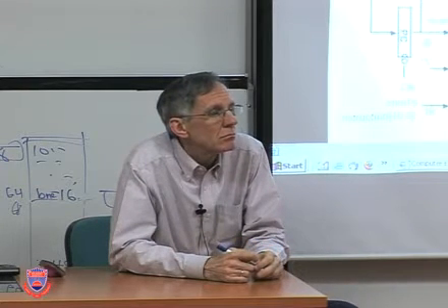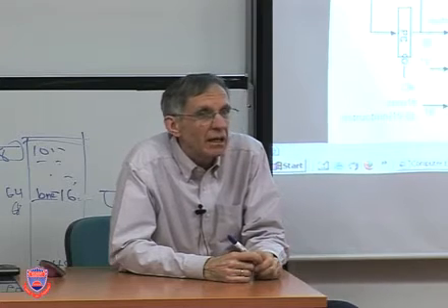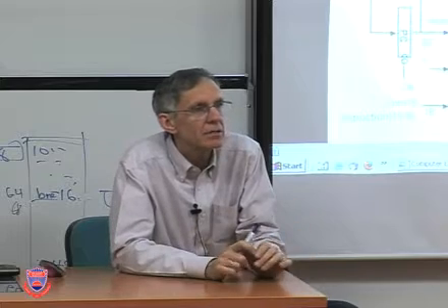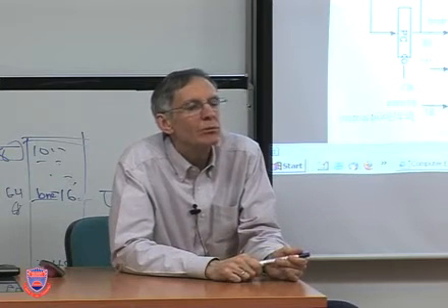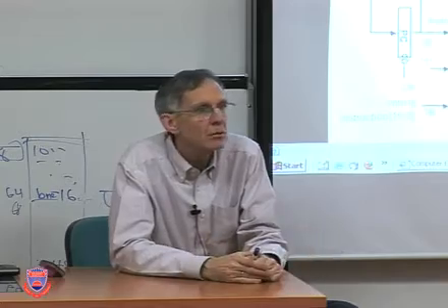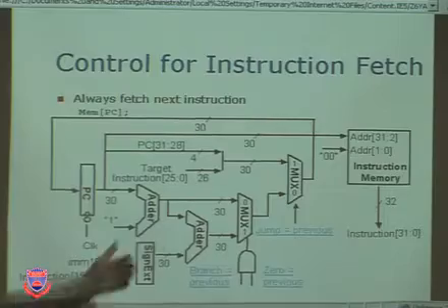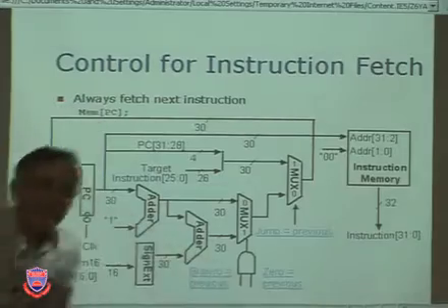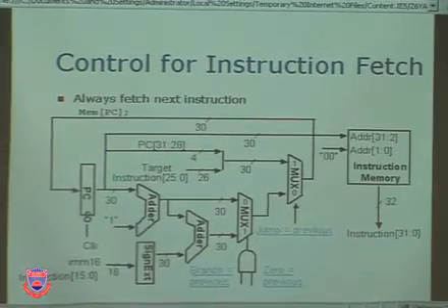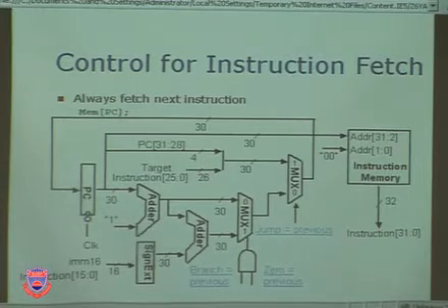So, yeah, remember, it's acting combinationally. Inputs now determine outputs just a little bit later. We said that. We said that memory that you only read from acts combinationally. Combinational circuits don't, at least this one doesn't need to have any control signals. You might say, oh, the control signals are the addresses. They tell you which data to get out. You could say that. But it's not coming from the control unit, so it's not blue. So there aren't any control signals for reading from instruction memory.